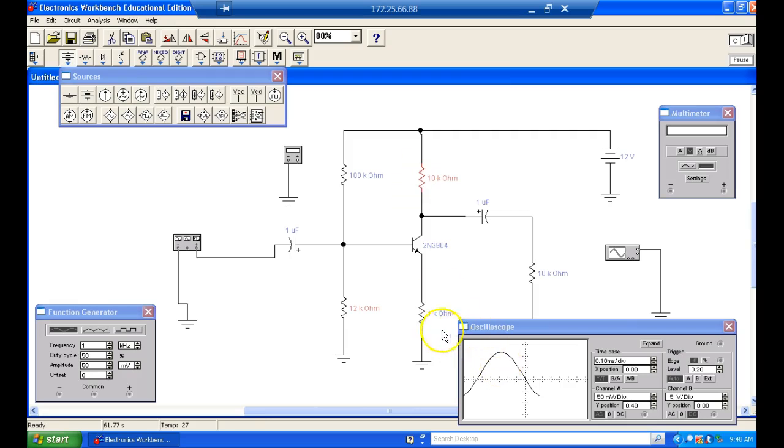So this resistor right here is seen as times beta. Beta is IC over IB. We just lost IC, guys. So we lost beta. So now this guy here is seen as a 1K resistor. It's not seen as a 100K anymore. It's seen as a 1K. That 1K is setting the base voltage right there now. Not this right here. Right?